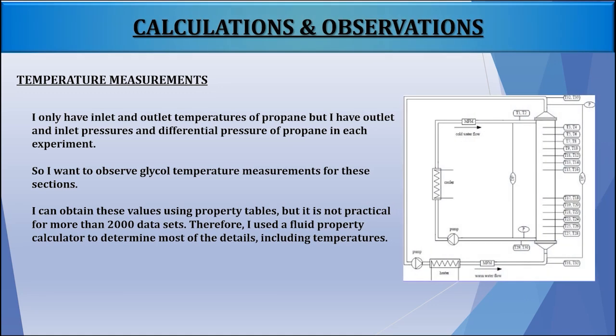For the temperature measurements, I only had inlet and outlet temperatures of propane. However, I also had outlet and inlet pressures as well as the differential pressure of propane for each experiment. To ensure accurate calculations, I also observed the glycol temperature measurements for these sections.